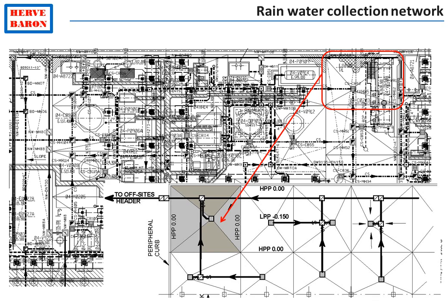The rainwater collection system, for instance, is a rather intricate collection of catch basins and pits at every change of direction, to be able to clean in case of blockage. In fact, there is not only one such system, but two systems in a process plant. One for clean water, collecting the rainwater on building roofs and roads, and one for oily water, collecting water on the paving of process areas. So you see that this system of rainwater collection is rather complicated.